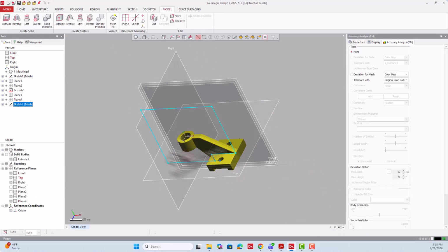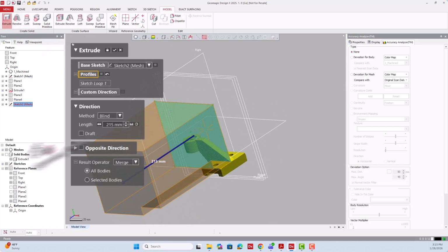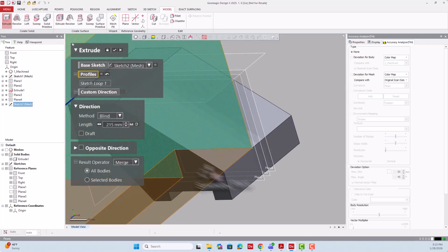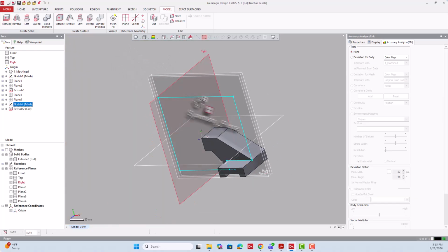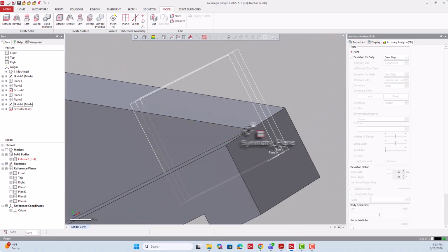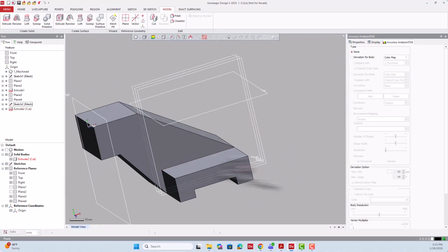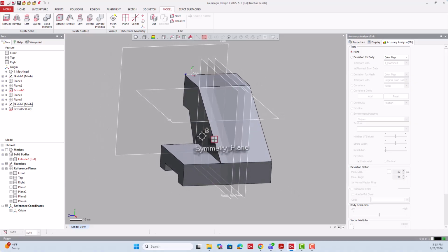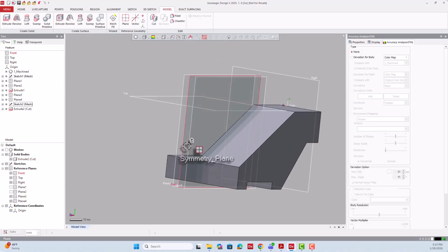So now here we have made this particular shape, and we can say extrude, and here note that you can give an extrude and use a cut option. So when you do the cut option, you'll observe that it is cutting exactly at these points without leaving any other lines. So we'll look into this on the other side as well.